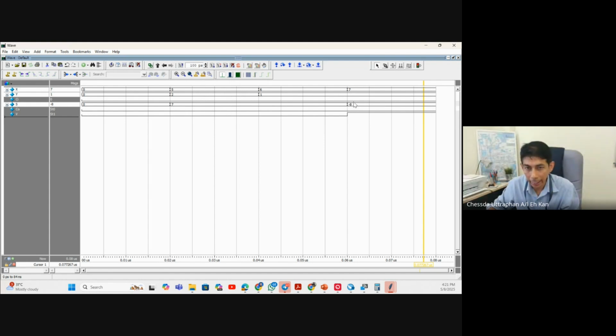This is minus 8. Okay, if you can see, this is minus 8. This is wrong, you see, because x is 7, y is 1, and 7 plus 1 should be 8, but you have minus 8. But you see the overflow indicates that, okay, this is overflow, b equal to 1, meaning that the result does not fit. And this is overflow.